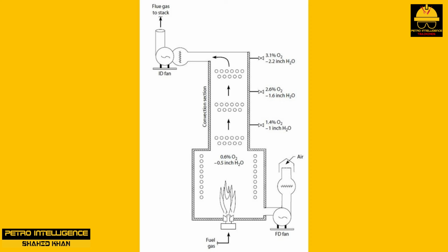If the airflow to the firebox becomes very severely low, then one or more of the burners may be extinguished through lack of oxygen. If the fuel is then left to flow unchecked, it will build up in the firebox until eventually enough tramp air has been sucked into the firebox, at which point the extinguished burners may be reignited by the heat left in the refractory walls, causing a minor explosion or a detonation as it ignites. The magnitude of the explosion depends on the degree of oxygen starvation.